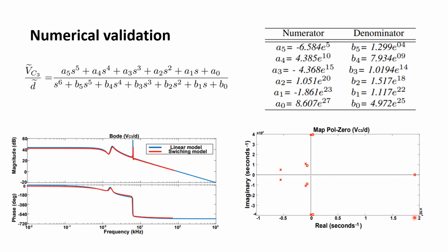The poles and the zeros of the frequency response of the output voltage transfer function with respect to the duty cycle were also determined. It is important to note that this is a non-minimum phase system, where three right half-plane zeros are present. This system exhibits complex dynamics in terms of voltage regulation.